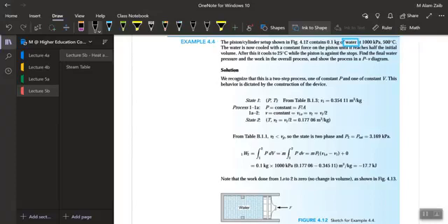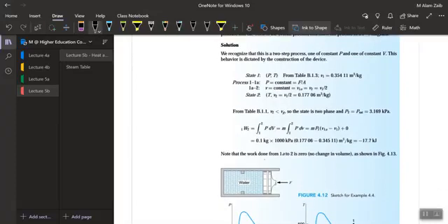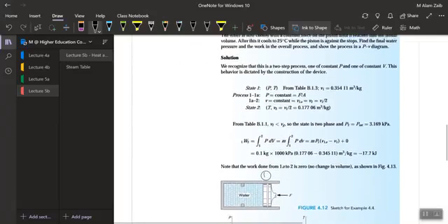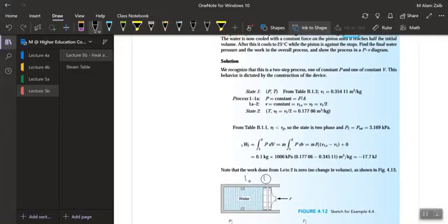So this is a problem of water, and we would be using the steam table. Initially we have got a piston and cylinder arrangement, state 1, and we are cooling the piston so it reaches half of its initial volume. So we have got 1A, which is half of the initial volume. The stop is at half of the cylinder. Then when the piston reaches here, the cooling still continues to 25 degrees centigrade while keeping the volume constant, and that would be our state 2. We could write it as state 1, 2, 3 or whatever, but as the book says 1, 1A and 2, we will stick to 1, 1A and 2.